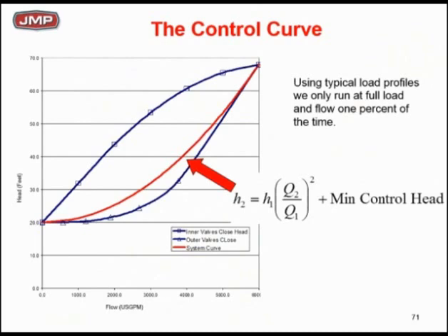If the two-way valves furthest from the pump are asking for the 3,000 GPM, how much head do I need? Roughly about 55 feet. So at 3,000 GPM, you can be anywhere between 25 feet and 55 feet of head requirement on this pump, and you have to have the pump speed to get you there, and the horsepower to get you there.